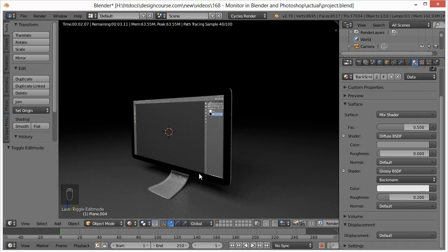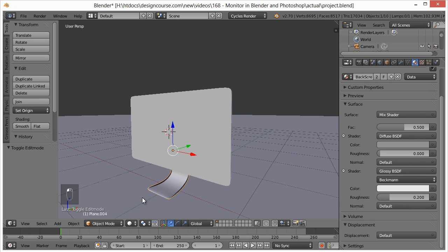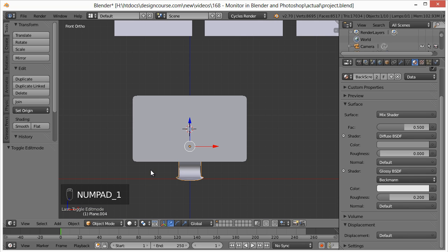So now what I want to do is create kind of like a path. So in Photoshop or Illustrator, for example, you have the pen tool, and that allows you to create paths. So I kind of want like this path that's coming from the screen and wrapping around it. So the way we can do this and create basically a wire is we'll go to solid mode here, and we'll hit 1 on the keyboard, left click, wherever we want the thing to start coming out.